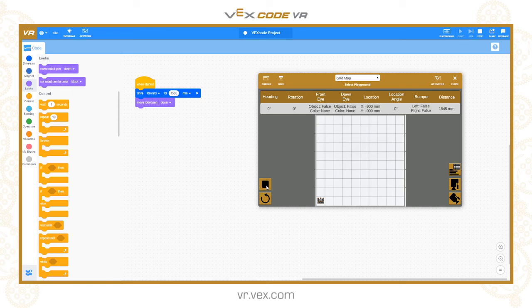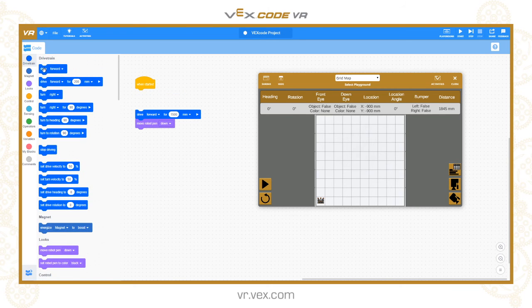So until the robot finishes its journey. Here you can see this is flashing, it's driving forward 1500, and now the pen has gone down, because this was a blocking command. It stayed in this one. A non-blocking command is the drive forward command, because it doesn't have a parameter attached to it.